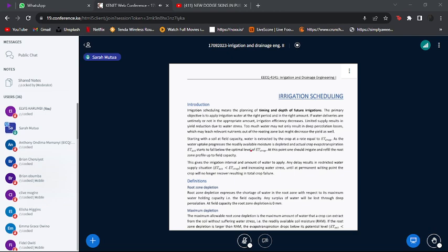So when you dip that sponge fully in a basin, you are going to see the bubbles in the pore spaces of that sponge come out, and at some point that sponge is going to be fully saturated with water. So we could say the moisture content of that sponge at that point is moisture content at saturation, or saturation moisture content, which is usually equal to porosity.